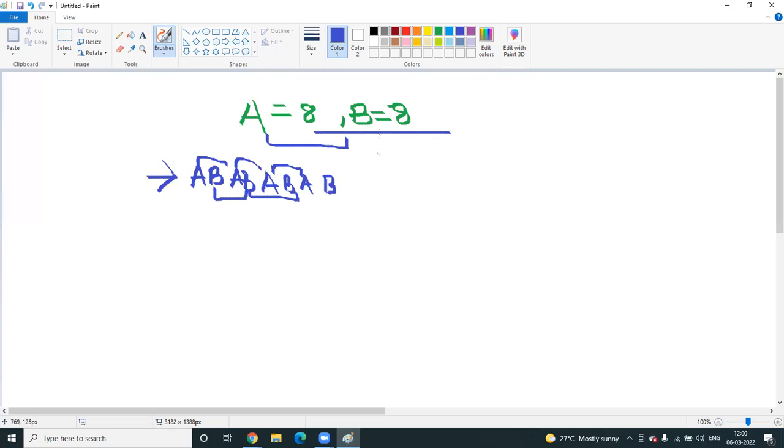Second, we need to do common centroid. Because this is a critical matching, we have to follow certain rules. The first rule is it should be symmetric about the x and y axis. How will it be? If you maintain the first quadrant equal to the third quadrant, and the second quadrant equal to the fourth quadrant, whatever the element will be there, it will be the same. This is the main point.